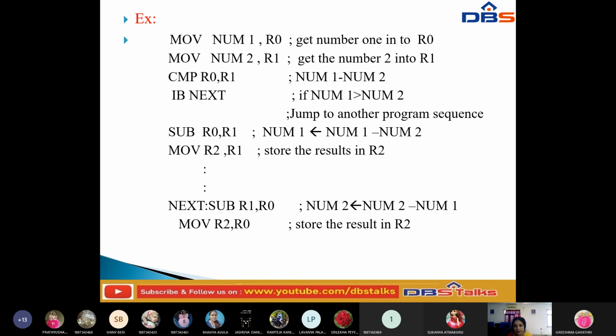The next instruction is move number 2 into R1. So in the R1 register, the number 2 value is stored. Now I am doing the comparison between R0 and R1. How is the comparison done? We compare as number 1 minus number 2. We take some value for number 1 and number 2, and then compare the two.